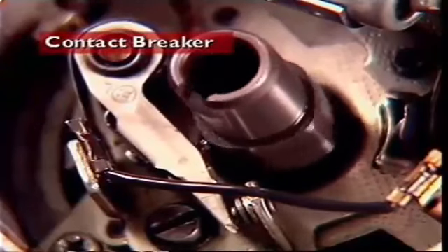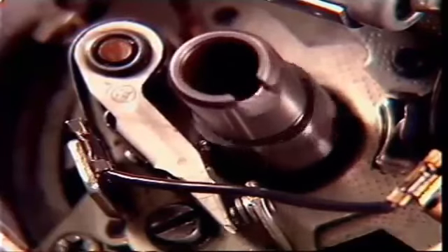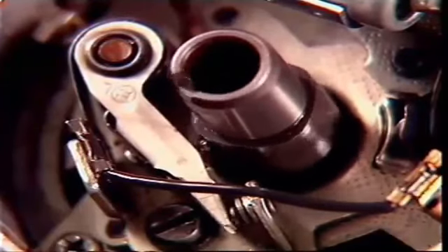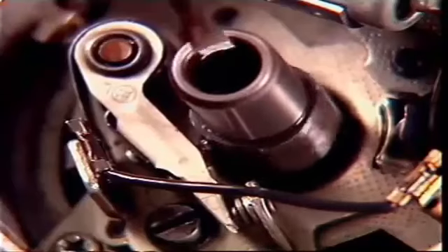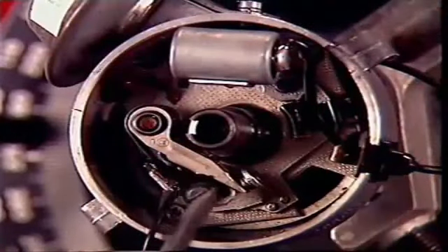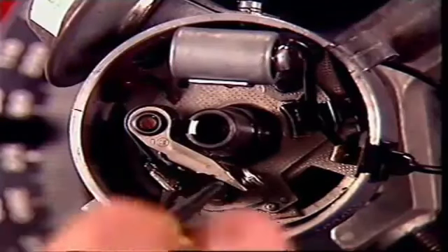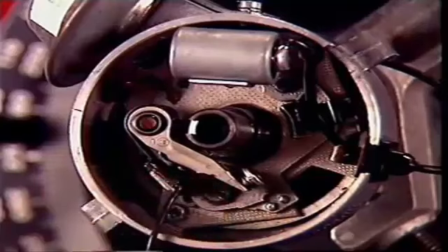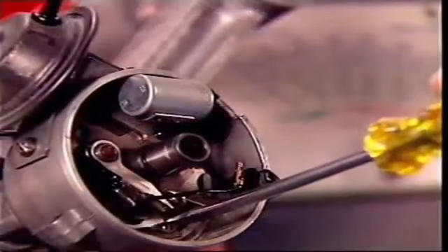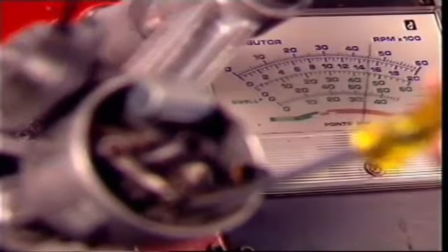The contact breaker is a mechanically operated electrical switch which is fixed to the distributor base plate and opened and closed by the distributor cam with the rotation of the engine. The contacts normally form a self-contained unit fixed to the base plate by a retaining screw engaged in a slot in the fixed contact. The slot allows for adjustment of the contact breaker gap and the setting of the dwell angle when fitting or servicing.